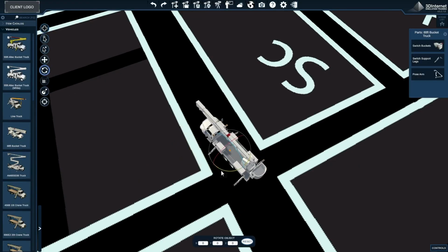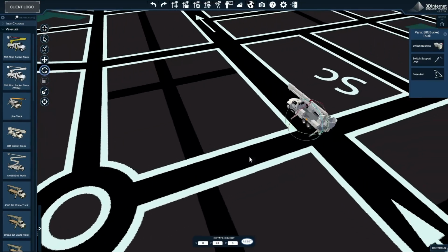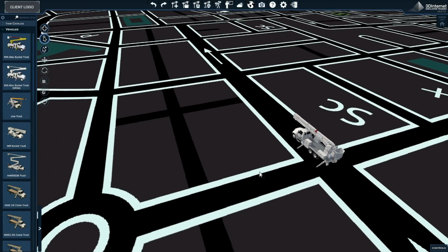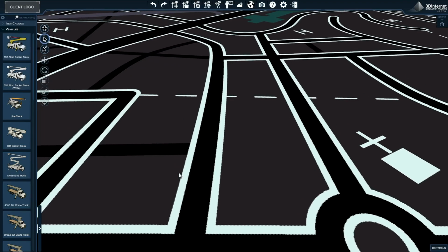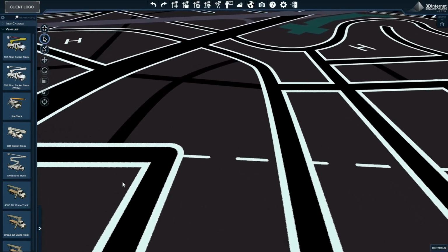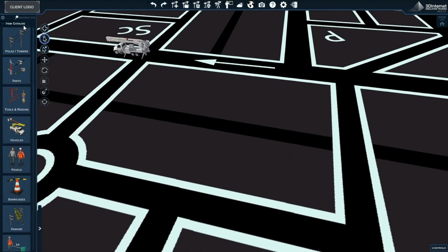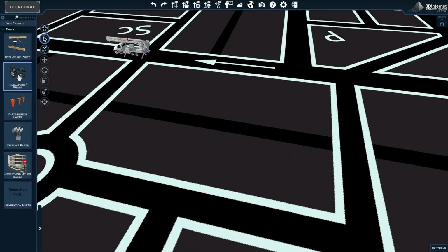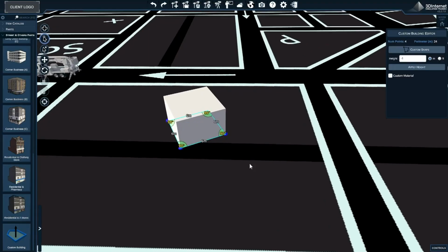Site plans and urban planning drawings will often contain building footprints within them. The custom building object is ideal for extruding these building footprints into their 3D counterparts. Let's do this now. Under Street and Other Parts within the item catalog, there is a custom building object which can be dropped. Once dropped, you'll notice a simple building with 90-degree angles and a default material.